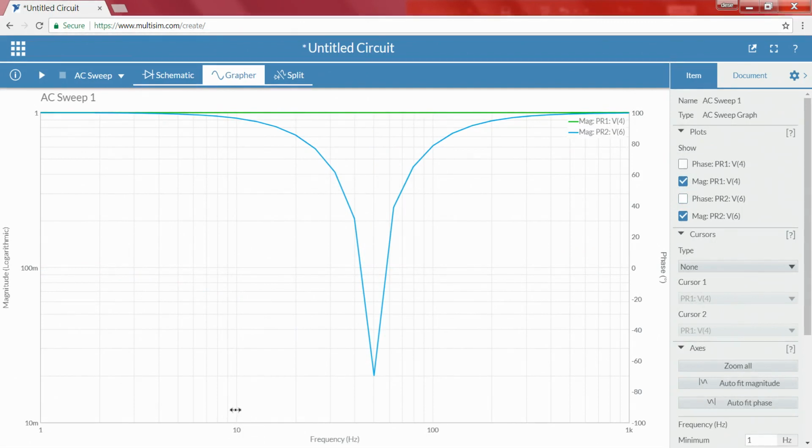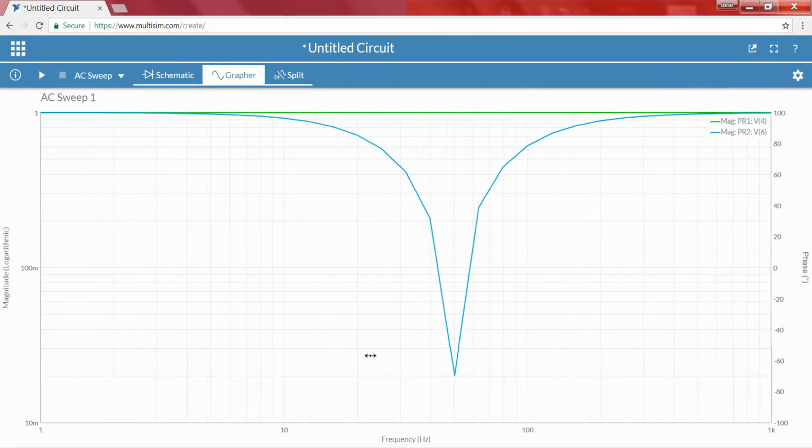If you recall how we measure in a frequency domain, in a log scale basically 10, 20, 30, 40 and 50, right, 60, 70, 80, 90, 100. Now, we need to know the 3 dB line, this 1, 2, 3, this point, right. The frequency at this particular amplitude is generally the cutoff frequency.